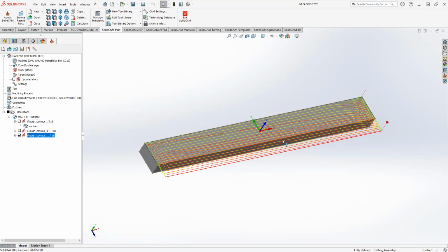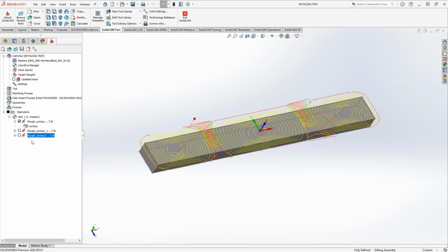The very last one, doing this path right here. Now it looks like, you know, it wouldn't be, but it all depends on the material too. But all these long drawn out passes right here and then moving back over is going to eat up more cycle time than using a separation channel by default. So what we're trying to do with iMachining and the algorithm is make it into as many equal squares as possible so that the tool can stay in constant contact, just doing a nice spiral to really make that cycle time more efficient. Plus the chip control, you can see over here to here, our tool path actually changes based off of that tool control that's going on there. So that's the reason why they switch it.